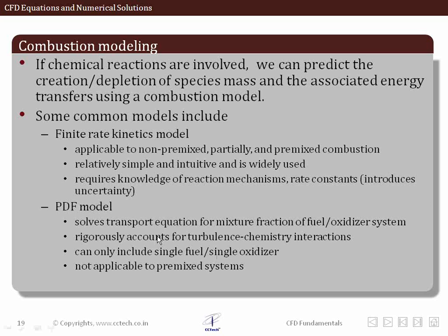Combustion model, again, we may also try to include some additional equations for the combustion model. These usually come up as source terms in the different species equations and energy equation. They act as the source or sink of energy depending on whether the combustion is exothermic, as in most cases, or, in some reacting flows, an endothermic process. So we may also include some sink in the energy equation.